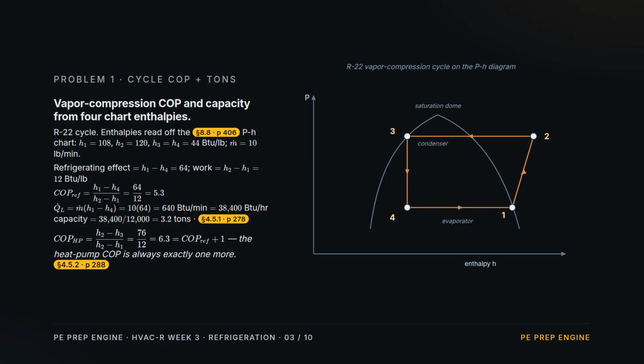Notice the heat pump COP is exactly 1 more than the refrigeration COP. Same compressor, and heat rejected equals heat absorbed plus the work.